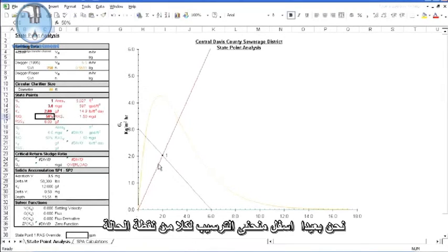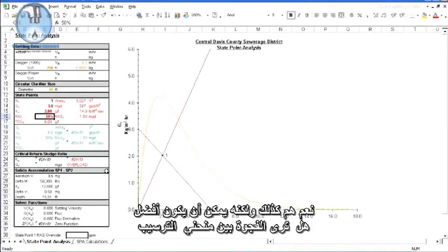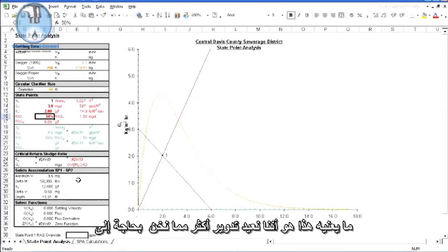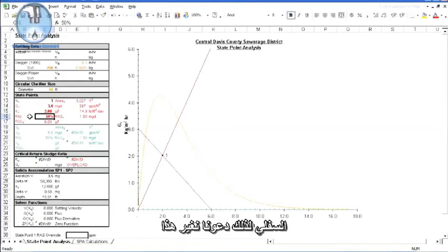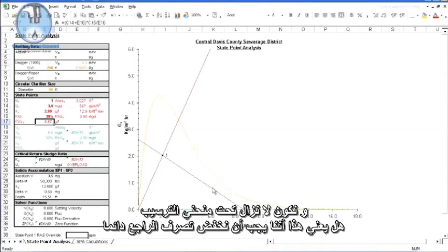We are way under the curve both in the state point and the underflow rate line. Life is good, right? Birds are chirping and so forth. Well, yes, they are, but it could be better. You see, the gap between the settling curve and the underflow rate line represents wasted energy. What this means is we are recycling more than we need to. As we mentioned earlier, a lower RAS flow results in a flatter underflow rate line, so let's change that. In this case, we can drop our RAS to about 30% or 0.9 mgd, and still be under the line.